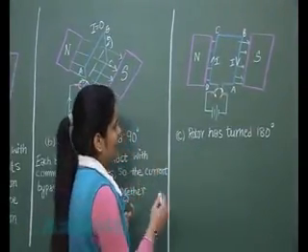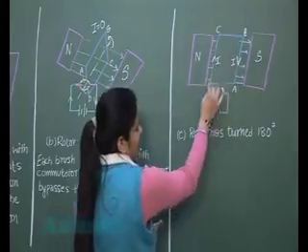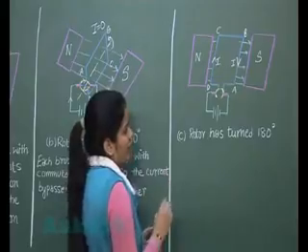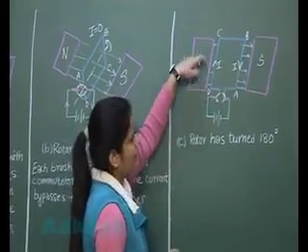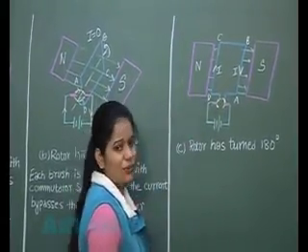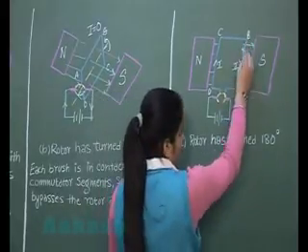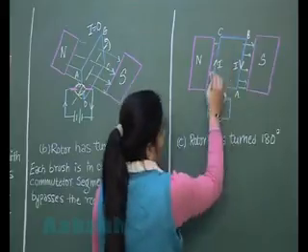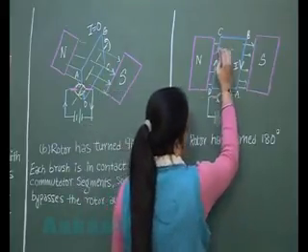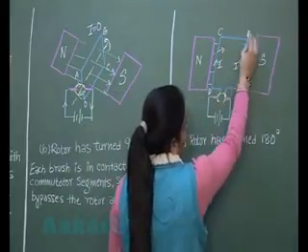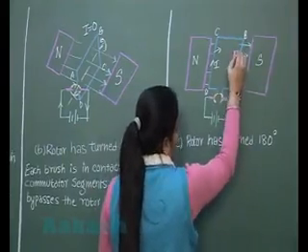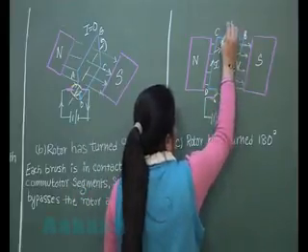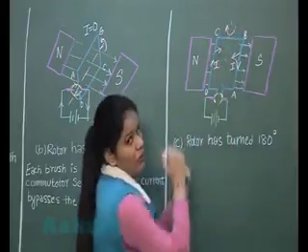Now student, in this case, CD is along this side and AB is along this side. Now current through arm CD is in the upward direction as shown in the figure, and in arm AB it is in the downward direction. So on arm CD now force is acting inward, and on arm AB now force is acting outward. So student, this armature will keep on rotating anti-clockwise.